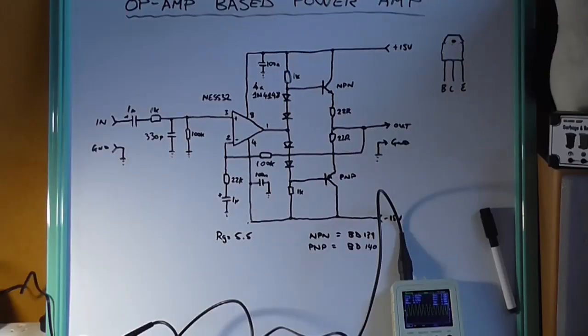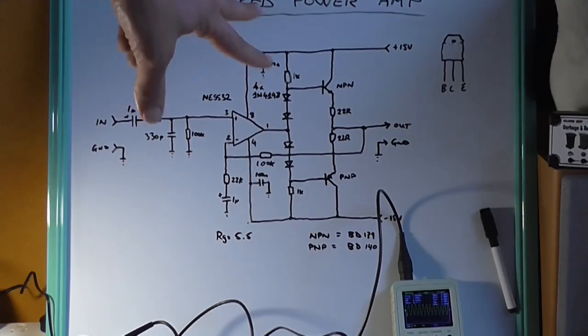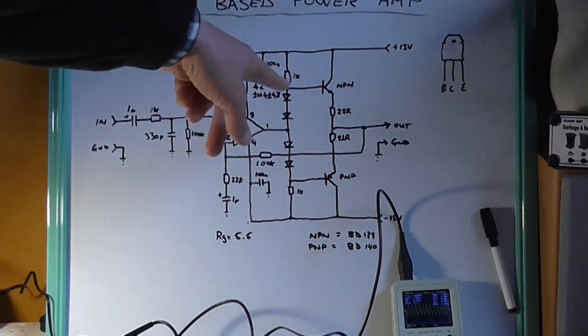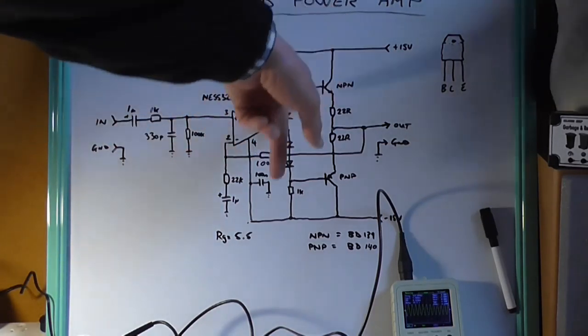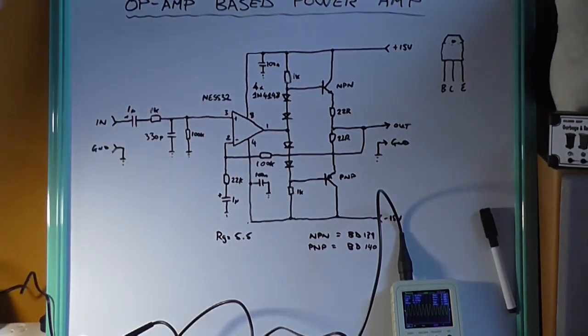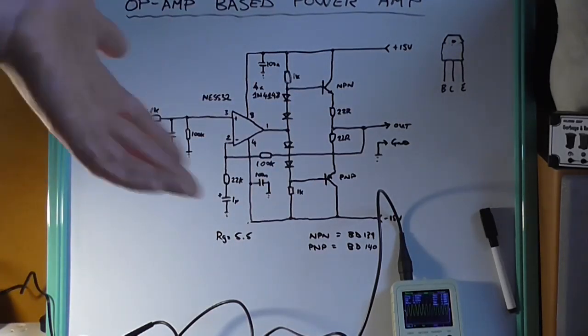The actual circuit here is designed to power headphones. Now if you wanted more power out of it, you would have higher voltage power supply lines coming in using the current output transistors I'm using, or MJL series, whatever, or even a TIP31 and TIP32C respectively.